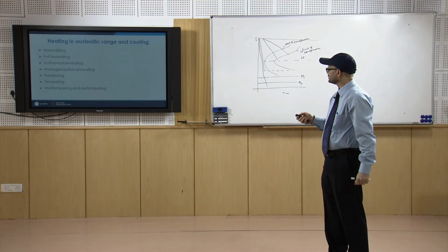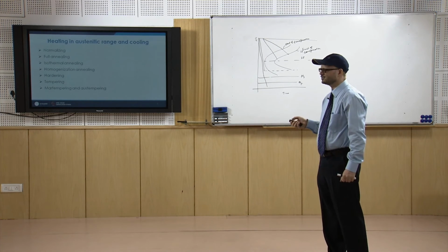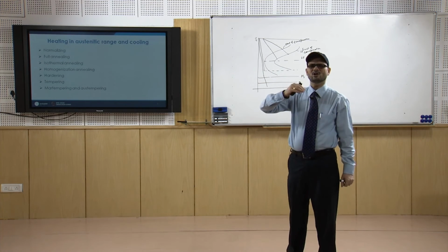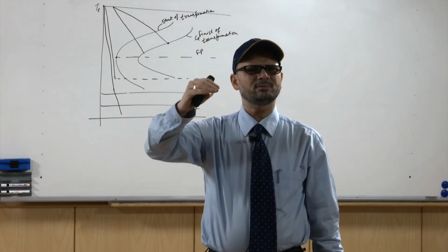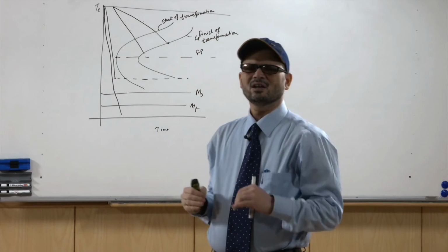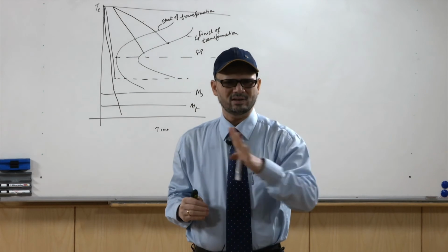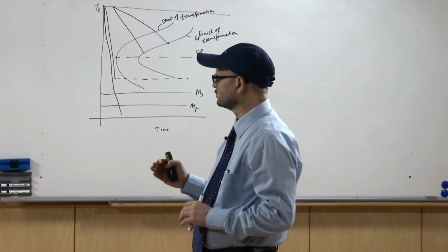So, for increasing the hardness you go for this hardening treatment, in which you are heating in the austenitic range, 50 to 100 degrees centigrade above A3 or ACM, and then quickly quenching it into oil, water or any suitable solution like brine.